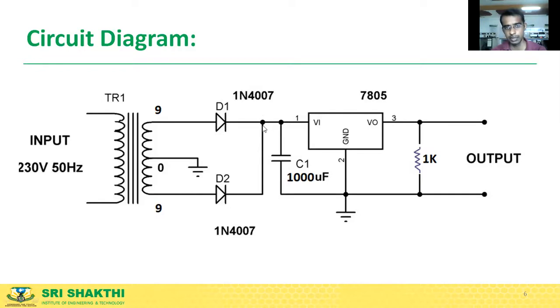Here, without employing the capacitor and regulator, we are going to see the ripple content. Then, employing the capacitor and the voltage regulator, we will see the output voltage. Here we'll have a load resistance of 1K, and also a DRB to vary the resistance and see how the voltage is getting regulated. That's the setup arrangement and the circuit diagram.